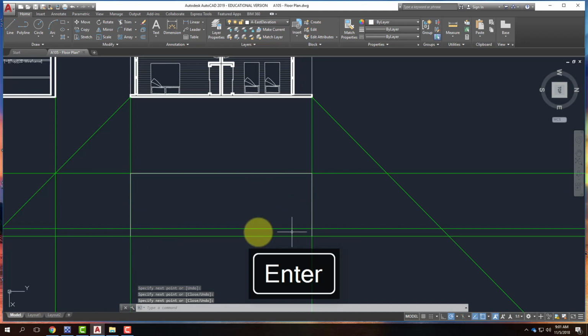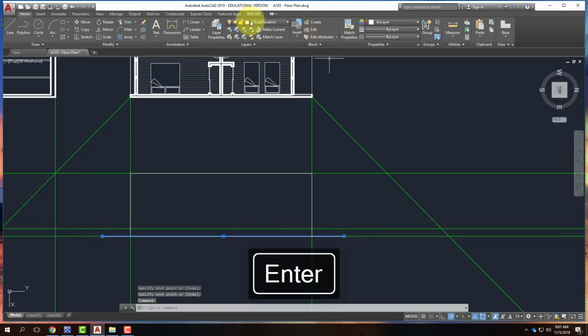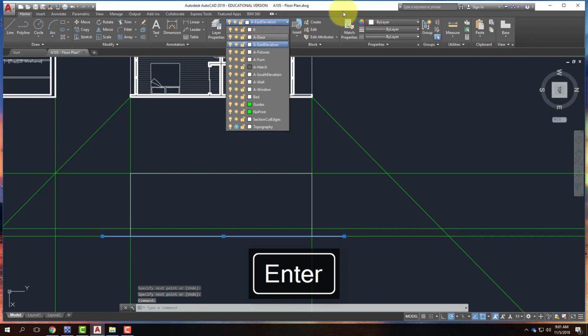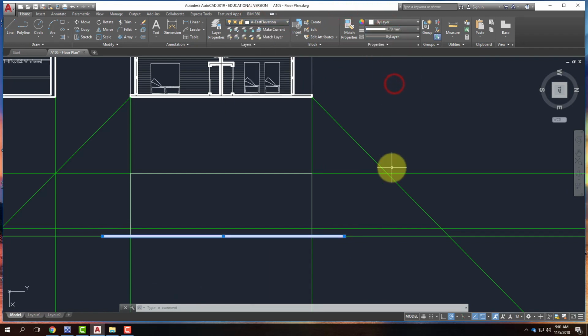It's basically a box. I need the ground plane still. So I'll do a line. We'll come over like that. I'll select that line. And oops, sorry. This needs to be nice and thick. So we did it at 0.7. And there's my ground plane for my building.